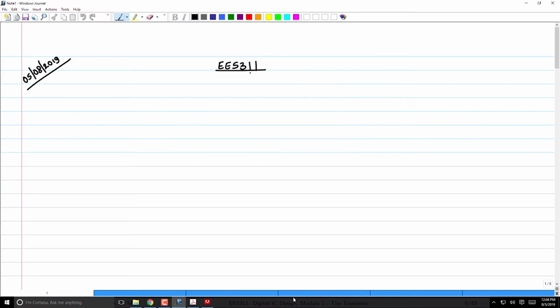Okay, so good afternoon. Let's get started. Last class, we were deriving the equation for the on current of a transistor, right? And we said that the on current we can show for an NMOS transistor is IDS equal to mu n C ox W by L into, I'll bring the VDS out, VGS minus VT minus VDS by 2.